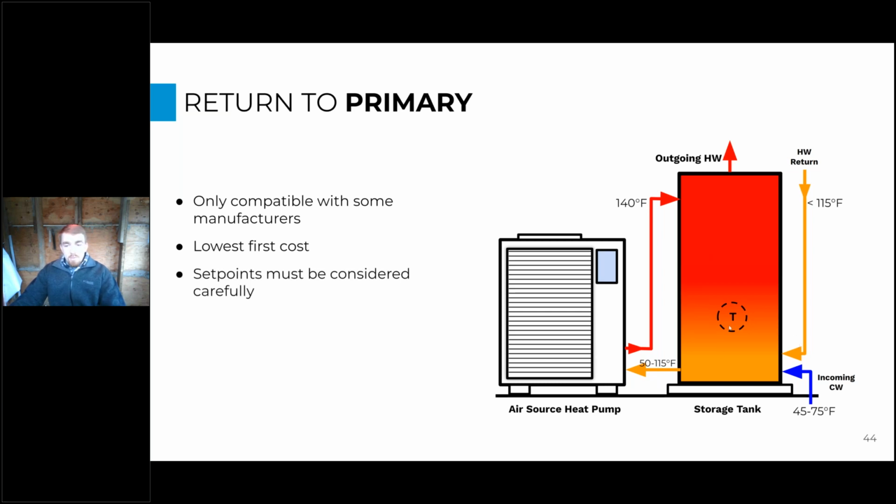And since we talked about the stratified storage tanks, and the temperature sensor actually registering a really high drop in temperature before the heat pump turns on, you have to be careful with this return to primary system, because you might not see that drastic temperature drop if most of your load is hot water return.